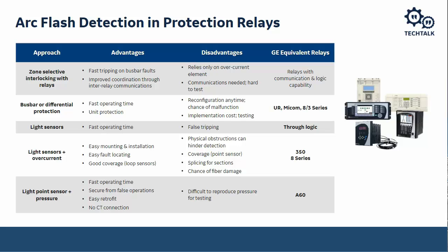Last one listed there is a light and pressure sensor. That's a nice concept because it doesn't require overcurrent, but it doesn't work well with air blast breakers, and it's very, very hard to test.